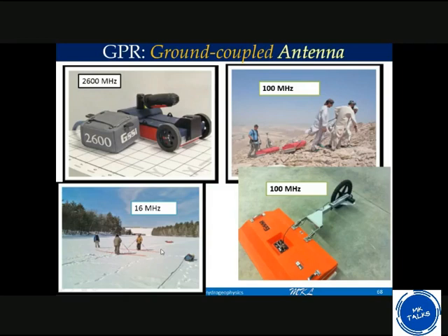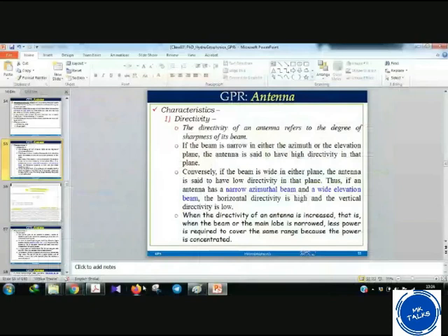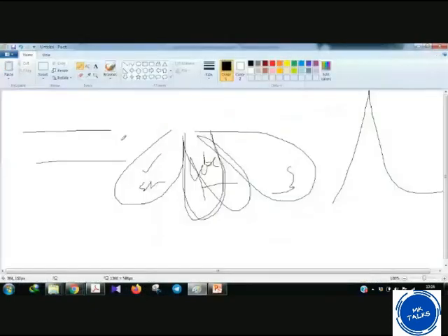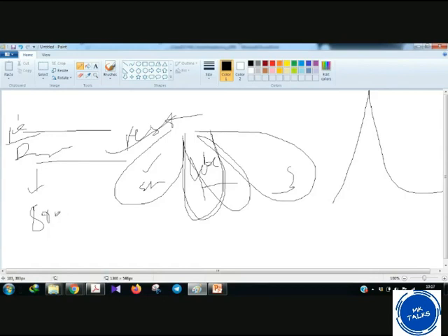Okay, so it's very difficult to take the data. So generally in glacial deposits it is working fine. One more thing, in our last class we discussed that if the overburden is resistive, then GPR is good enough. We don't go for any wet or moisture land area or soil covered area. We generally go for resistive areas, like where dry sand is there or ice is there. Okay, simple ice. So what happened in ice? In ice, you could map up to 800 meter to 1 kilometer using these antennas. Whatever antenna we're using, we get up to 35 meter in the sediment, and we get up to 800 meter in the glacier or this permafrost region.